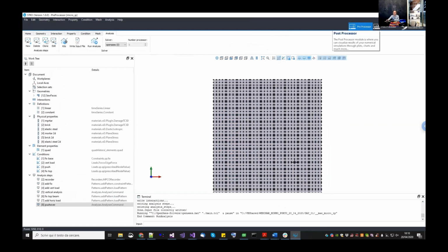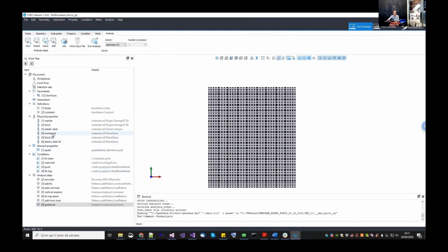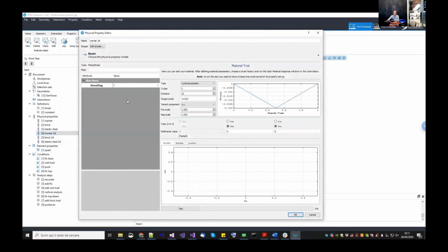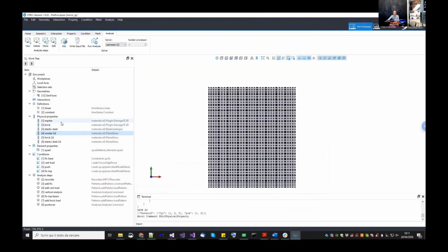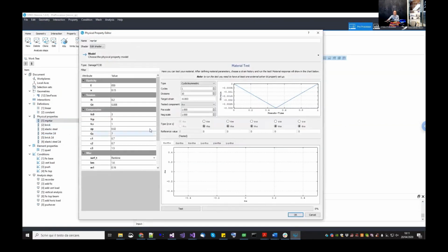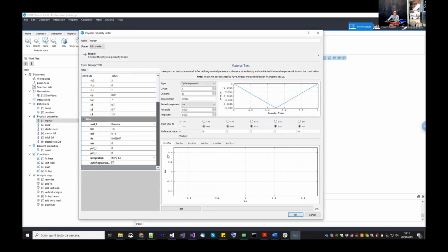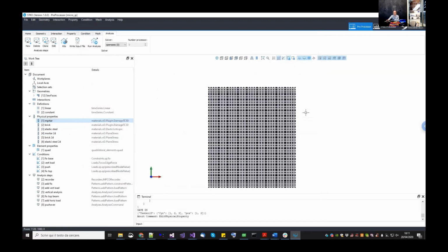Okay, this one has finished. As you have seen, it took at most 2 to 3 iterations, and this is thanks to the IMPL-EX algorithm. The IMPL-EX algorithm basically makes the solution stepwise linear. So theoretically it should take 2 iterations: the first one with the error, and the second one to zero the error. But in OpenSees, there is a different way in which they compute the residual, so it takes 1 extra iteration, but it is fine. So at least you are sure it converges.